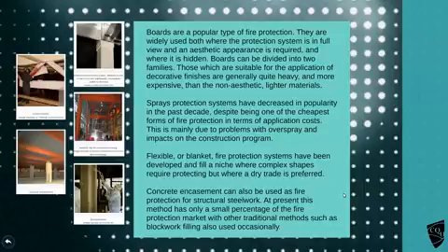So you can clad it with boards, gypsum boards or fireboard, boxed around it here. They're quite widely used, but they are open to impact damage if you're not careful. And quite often they'll cut a hole through it to put a service through or something, and they won't make good. As soon as it's got a hole in it, it's not providing the protection anymore. There's two families of boards: those that are suitable for decoration, so you can decorate them, and those that aren't. So you can choose. There's spray protection.